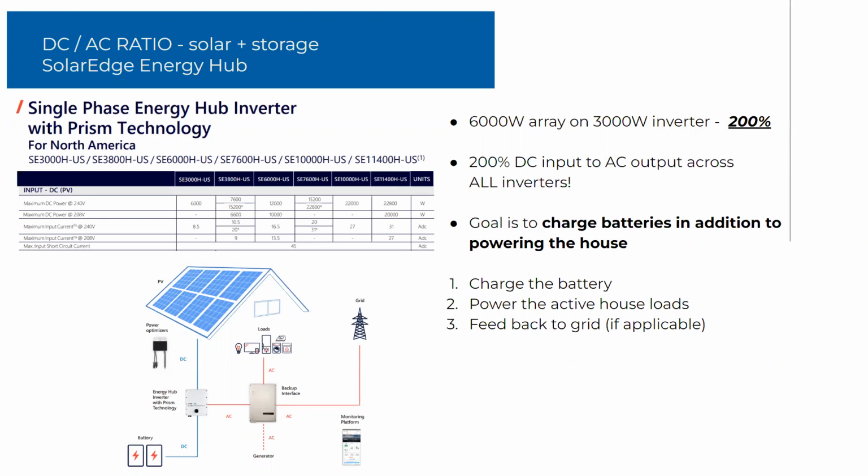So, because we have this extra need to charge the battery when we need to, we need more PV, because we want to make sure we have enough PV to charge any depleted battery and power active loads. So adding more DC power during this time enables us to oversize and not feel like we're wasting PV.